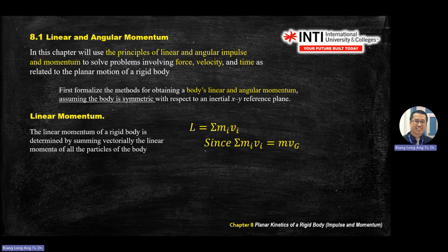And for a rigid body, we focus on what actually happens to the center of gravity. So we take the free body diagram on the left equal to the kinetic diagram on the right. So all the mass multiplied by the small individual velocities on the free body diagram will equal the mass multiplied by what happens to the center of mass.